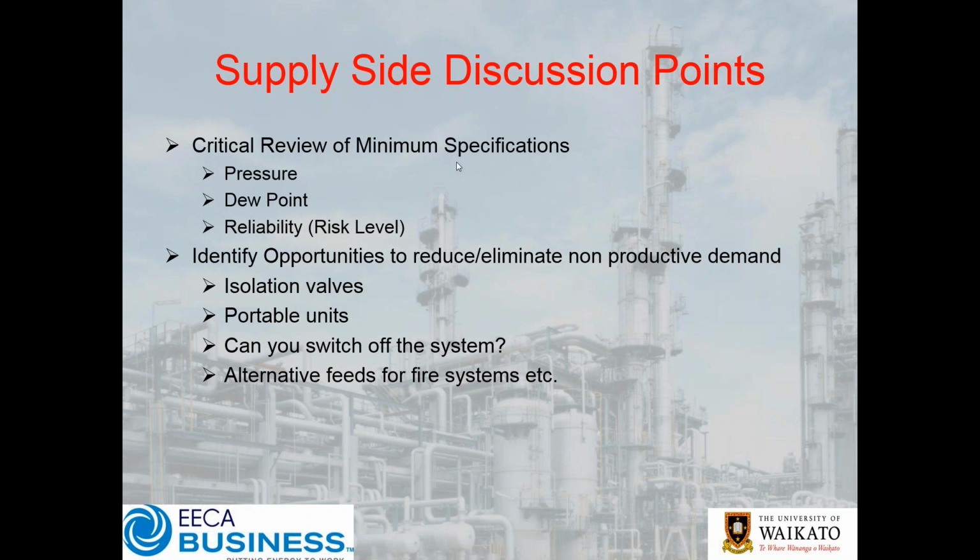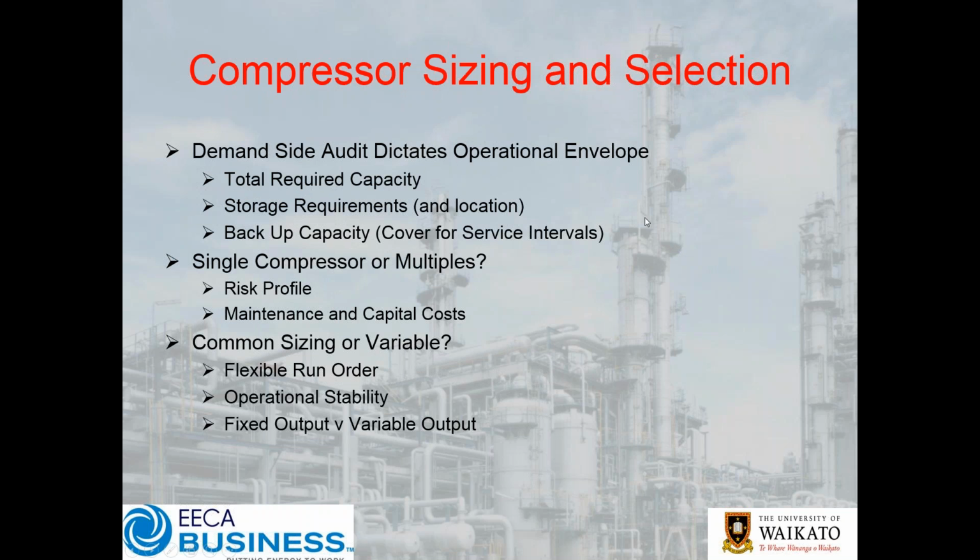So obviously those minimum specifications, as Nick has just raised a really good example, it's important to get that right. Equally, you don't want that dew point set point to be lower than it needs to be, because then all you're going to do is expend a whole lot of energy over drying your air. So yeah, it's really important to have a critical consideration of these things.